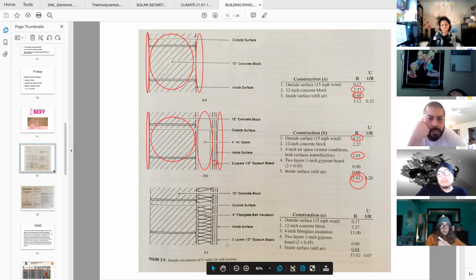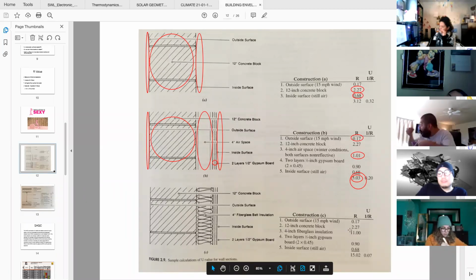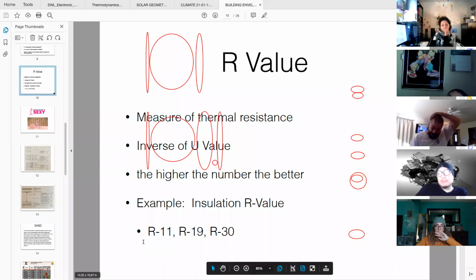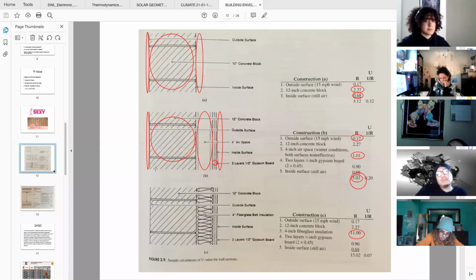And now moving on to the same wall, but putting in that insulation within that stud bay. So 4 inches of fiberglass. If you recall, when we were looking at our values up here, R11, a resistance value of 11, is the typical 3.5 inch stud resistance value.